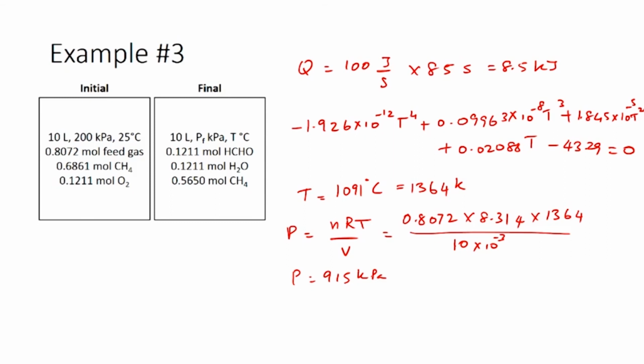However, in the second part of the problem, we have been told that the vessel explodes even though exactly that amount of heat is supplied. So, this is a problem, and we need to identify why that is the case. That is because you could actually have side reactions. The side reaction you would observe is a combustion reaction.